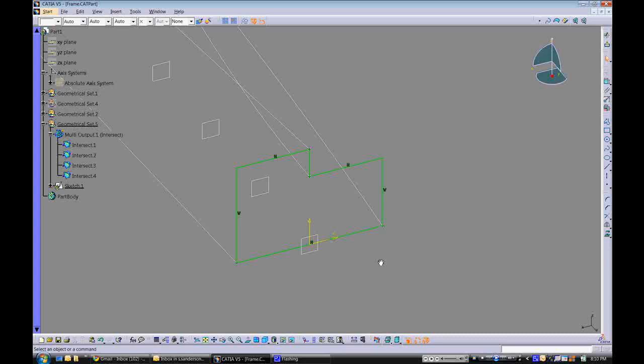There's also a visual indicator if you've over-constrained something. So let's say if we create a dimensional constraint here, you can see that everything turns purple, which is indicating that this is actually over-constrained, which is something that we don't want. So we'll go ahead and delete that. I just wanted to show you how over-constraining works.